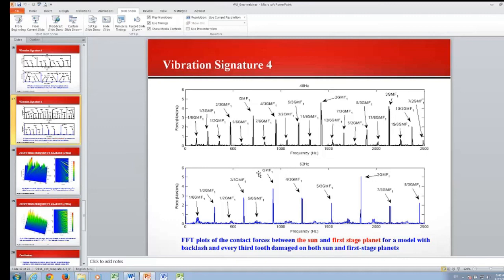Okay, so the definition for, thank you. This is another good question. Good questions. So the first one is the transmission error. Actually, the transmission error includes many kinds of errors. For example, the manufacturing error, misalignment of the bearing or the gear, and also the defect of the gear, the crack on the gear, right?